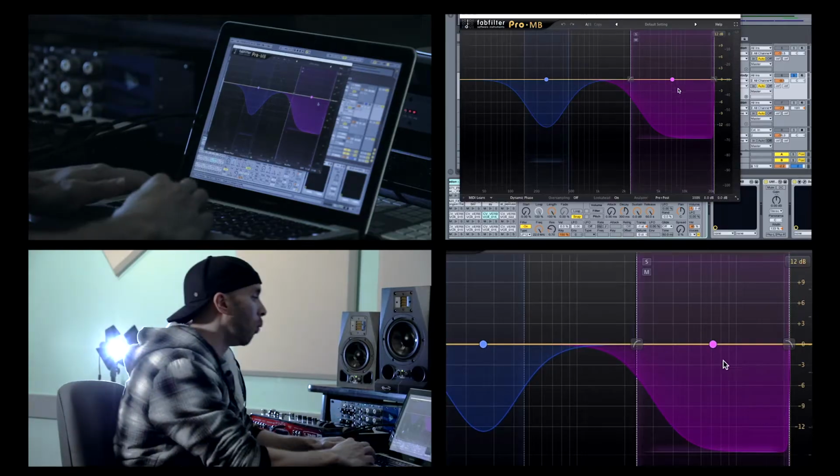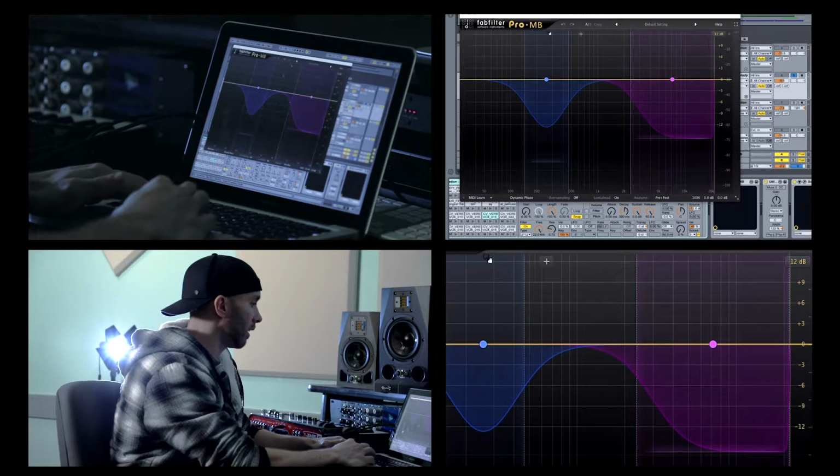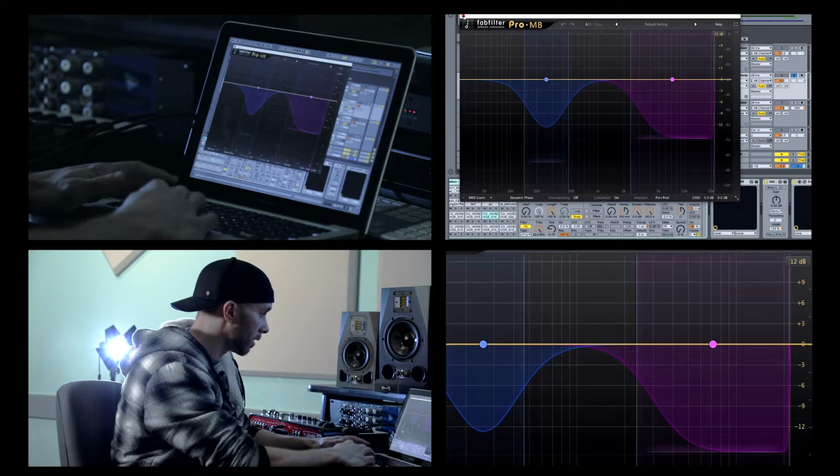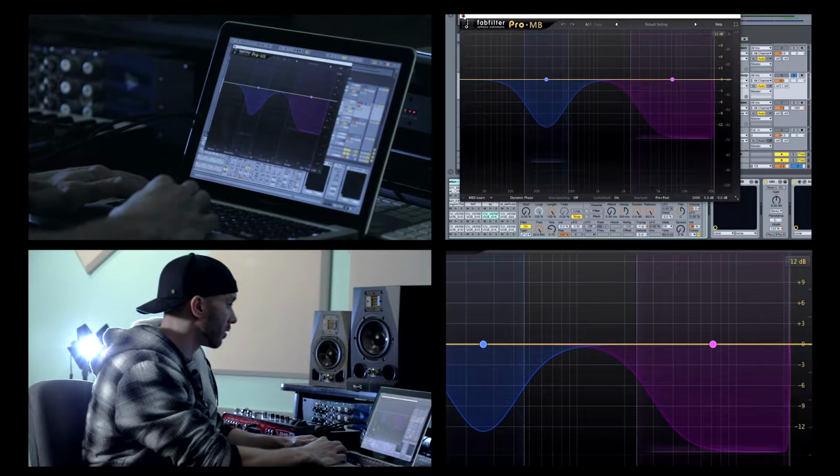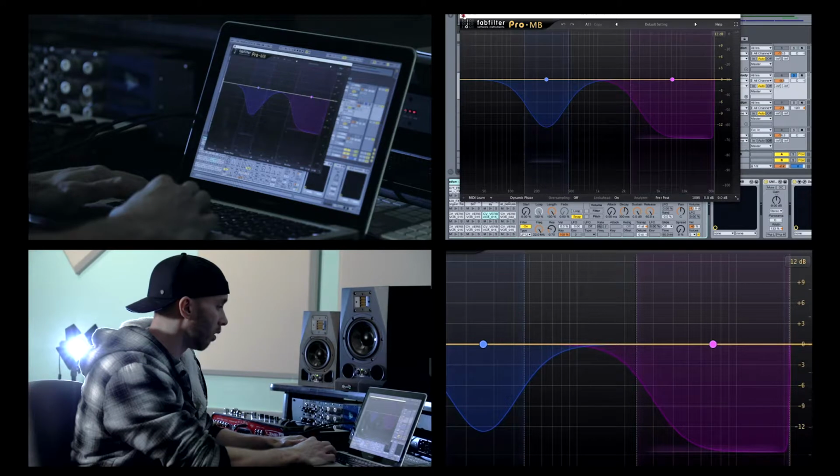And what happens in this case is every time a bunch of frequency information is present above 2 kilohertz, the compressor reduces that, therefore acting as a sort of automatic EQ in a sense, but it's actually compressing those frequencies. But one way to think about this practically is as an automatic EQ that only engages when it needs to. So let's see this in action. Let's watch the multiband compressor clamping down on this signal.